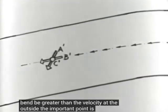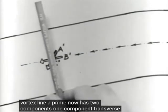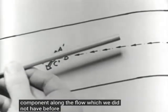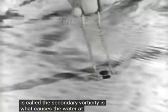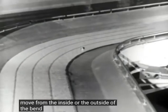The important point is that the vortex line A prime now has two components. One component transverse to the flow, which we had before, and a new component along the flow, which we did not have before. This new component, which is called the secondary vorticity, is what causes the water at the surface to move from the inside toward the outside of the bend.